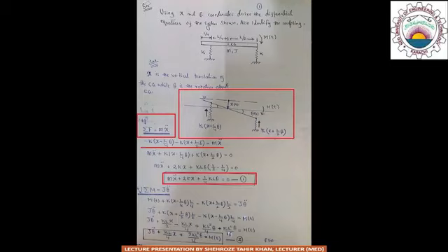So this is the equation of motion which is related to the first type of motion, which is the translatory motion. Next, we will consider the rotation of the bar about its CG, or the equation of motion, which consists of the moment produced by the stiffness elements of the bar around its center of gravity.